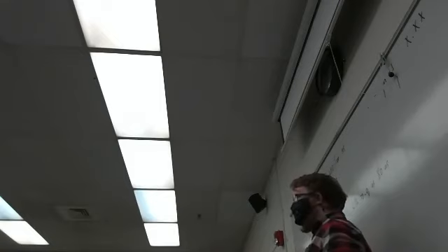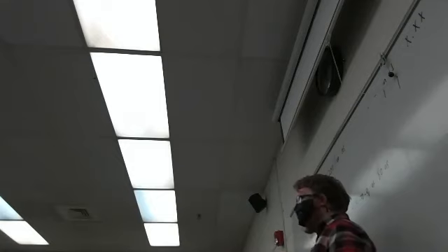It's literally just passing an address directly from a register, so it's one clock to Q of a D flip-flop. But we'll just say that the ALU has 50 nanoseconds. So just like Jason was saying, we'll have fetch, decode, and then execute.